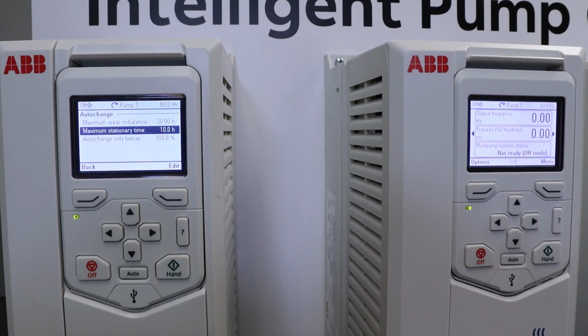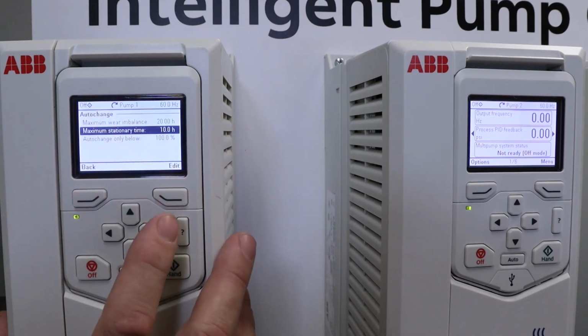That could be adjusted to like 90% or 80%, just so when you're doing a high demand scenario, you want to make sure you're below that demand when you're doing your auto change. But your auto change in our system actually does smooth auto changing. It will bring up another pump, and it will lower the pumps to even them all out and do the changeover. So, but this is the settings you can set.